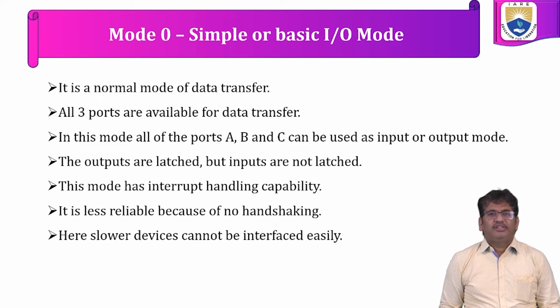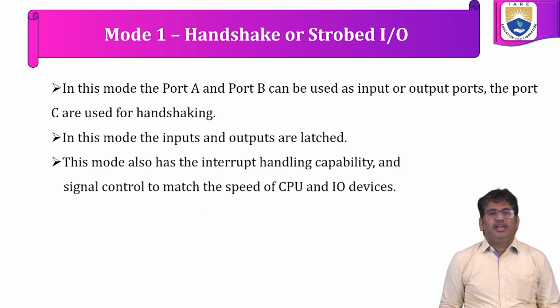If there are any slow response devices, we can't interface them with 8086 in this mode because of the absence of handshake signals.